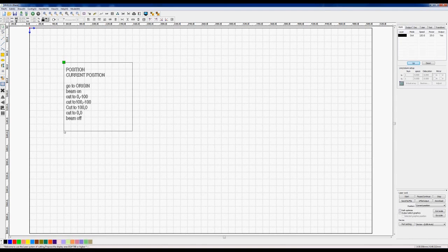Why minus 100 millimeters? Well, according to the Cartesian coordinate system that this machine works on, if you remember your graphical days back at school, down at the bottom left hand corner would be 0, 0. As you go up this y-axis, it's plus, and as you go right along this axis, the x-axis, it's plus. At this top left hand corner, our y-axis 0, 0 is there. So when we start coming down below 0, this is a minus coordinate for the machine. Even though it says plus and getting bigger and bigger down this way, it's actually a minus coordinate as far as the machine is concerned from its 0, 0. So anything going downwards is minus.